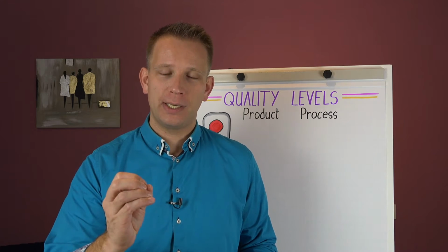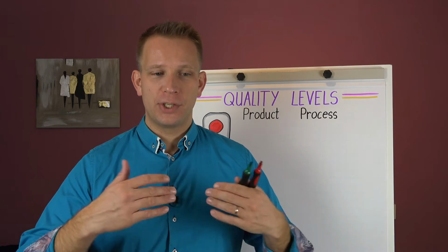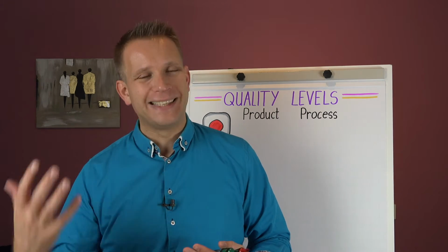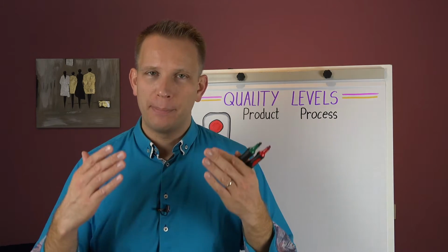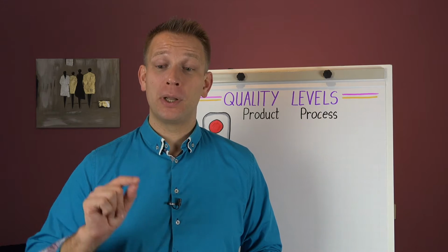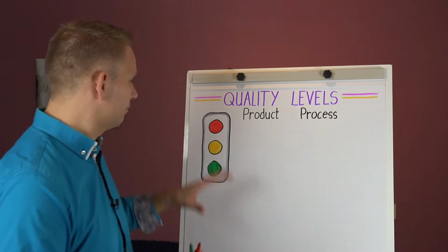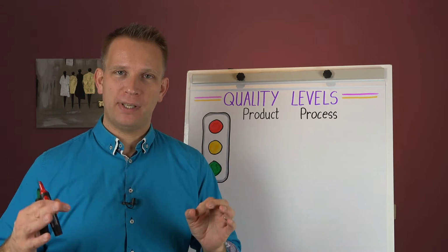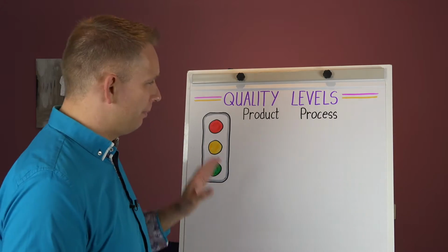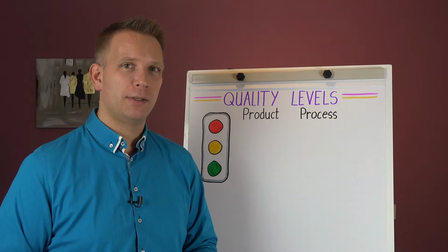This is an opportunity to make a very clear statement to your operators, to the whole production team, and make sure that you can also handle deviant cases, so defects, or that you make a clear message on when should you act, and maybe even more important, when don't you touch the machines. Now, for that, use a simple traffic light system, so a three level system. Yes, we can cheat a little bit on the red, but let's do the basic steps first before you want to make it too complicated.